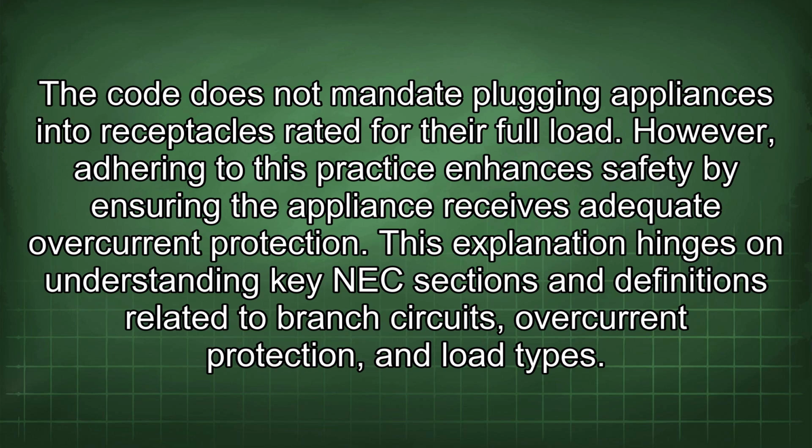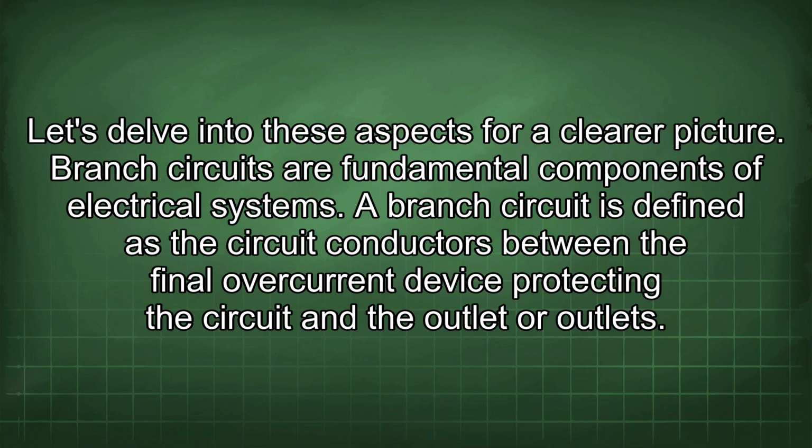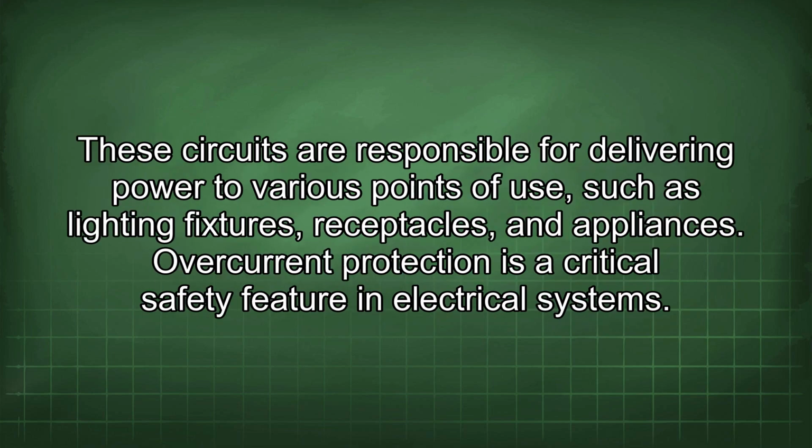This explanation hinges on understanding key NEC sections and definitions related to branch circuits, overcurrent protection, and load types. Let's delve into these aspects for a clearer picture. Branch circuits are fundamental components of electrical systems. A branch circuit is defined as the circuit conductors between the final overcurrent device protecting the circuit and the outlet or outlets. These circuits are responsible for delivering power to various points of use, such as lighting fixtures, receptacles, and